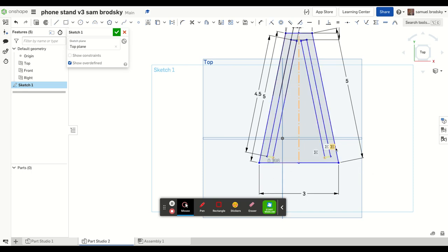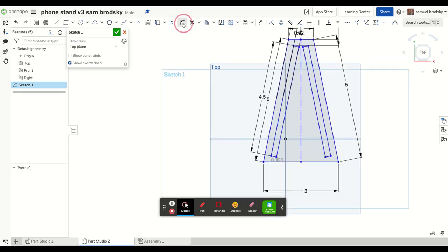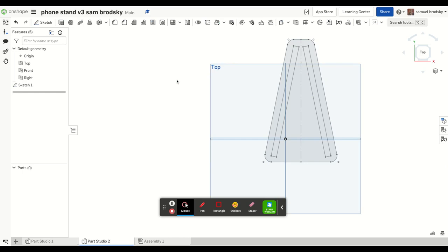And now I have these two, they're in the exact right spot. The only thing that remains is maybe some fillets, to clean that up a little bit. 1/4 inch fillets, looks nice on the other side, looks nice here. Don't want to fillet those interiors because that's where the stuff is going to fit. And, oops, I was supposed to double left click to accept it. Let me try that one more time. Double left click to accept it. Again, this looks pretty, and hit enter to accept the 0.25. Once I accept the sketch, it looks a lot cleaner.